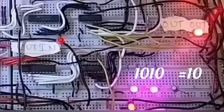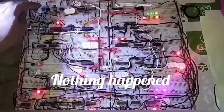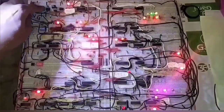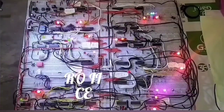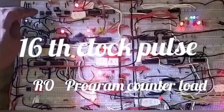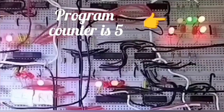That is, for the jump instruction program counter in, and for load A, register A in, and for load B, register B in will execute. In this situation, the third step is counter out and memory address register in, and the fourth step is RAM out and that particular register in.